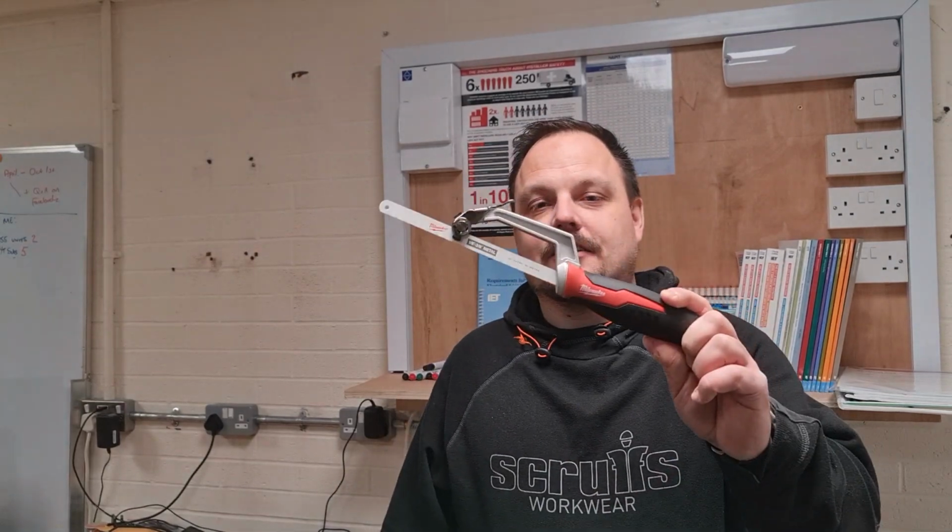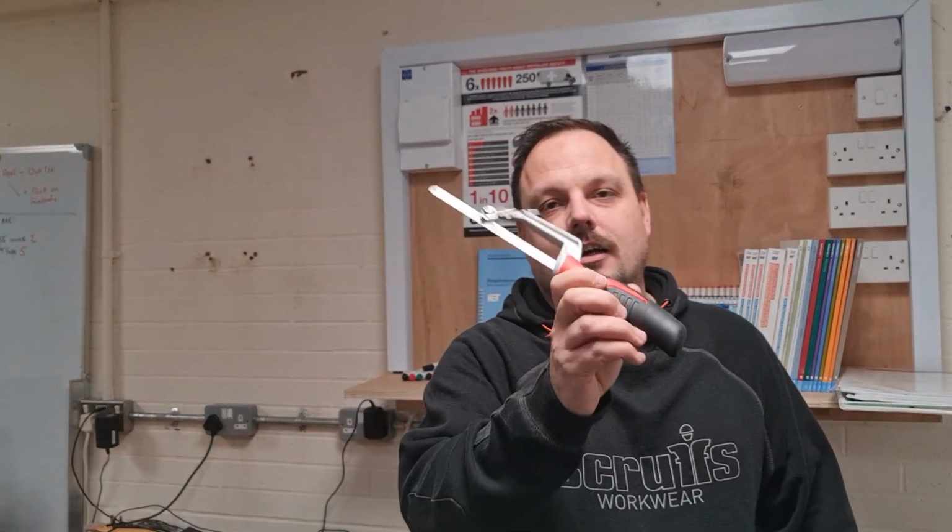There's this from Milwaukee. So this is their take on a junior hacksaw, if you like. We've all seen the steel wire armour cutting tools that you can get. So there's the CK Armour Slice. There's the name of the other one, I've forgotten now, but it's a bit like a plumber's pipe cutter where you spin it around and it cuts the tube. You can actually use plumber's pipe cutters as long as you've got the cutting blade that will do steel tube. It would also cut your armoured windings, but obviously they don't open wide enough for big cable. And you can't beat a hacksaw.